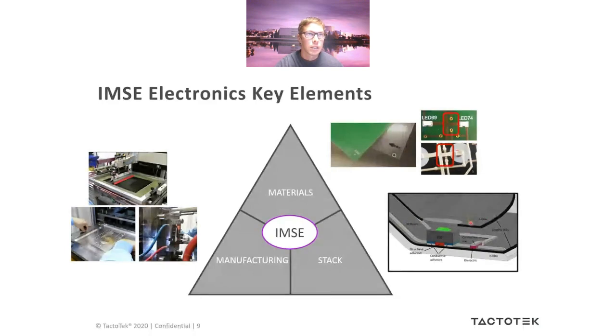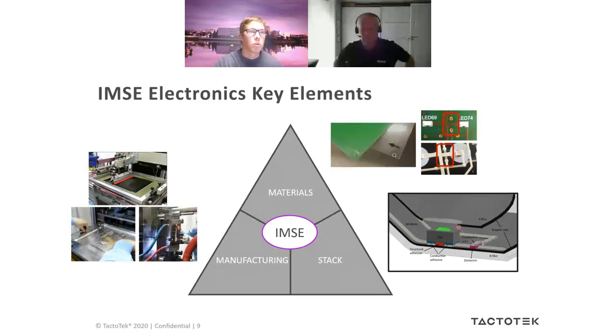This stack up actually defines how the electromagnetic field behaves within this structure. To achieve the performance required by our customer, we need to understand this whole stack and be able to simulate electrical behavior with, for example, 3D electromagnetic simulator tools.